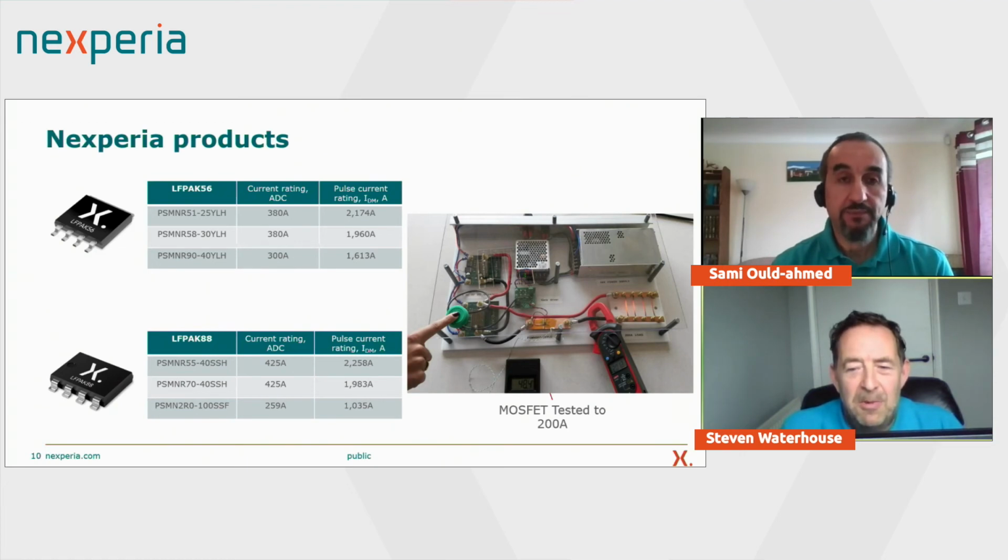For all of our lower voltage trench MOS products, our aim is to never sacrifice the SOA capability of a product in order to achieve the next gen. So what you would find is for a lot of our products, as we go to the lower RDS(on), we do that without sacrificing the SOA, and the SOA usually increases.